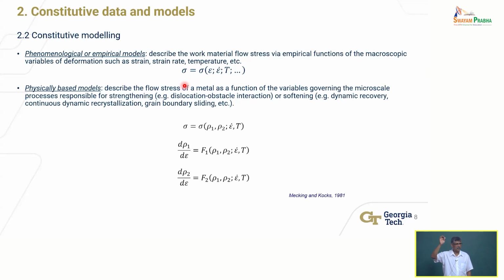Well, if it is a strain hardening material, the yield strength changes as a function of strain, right? From a stress strain curve, right? So this is describing, in its most general form, the stress strain relationship for the material. Okay, that is what this is saying. So this can be done empirically.